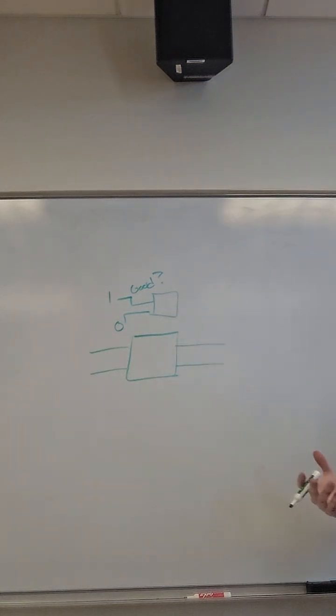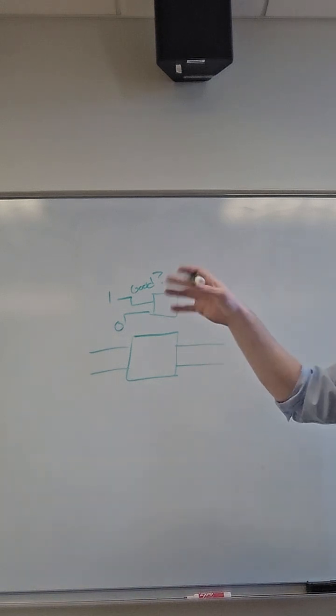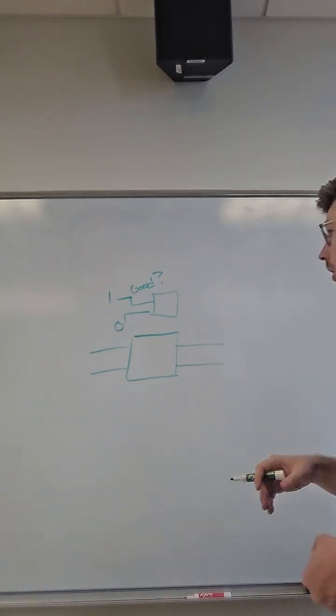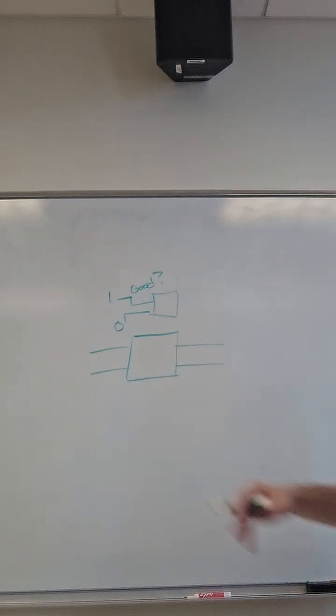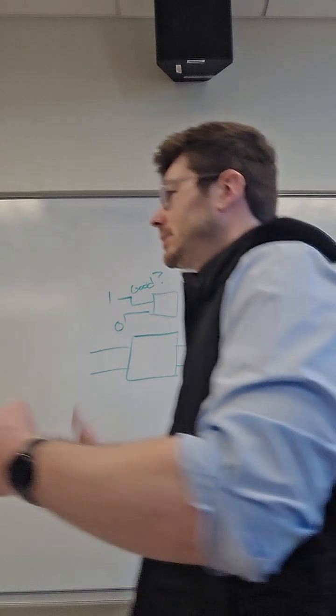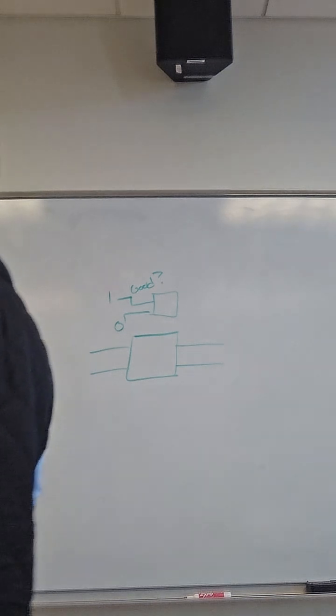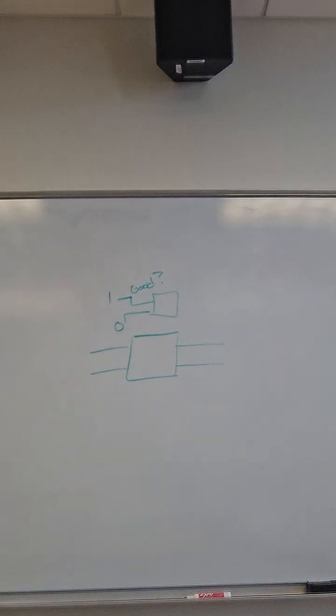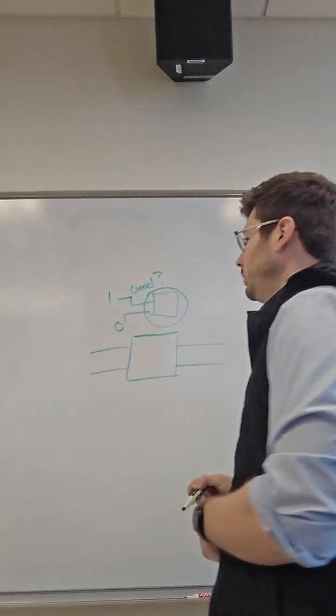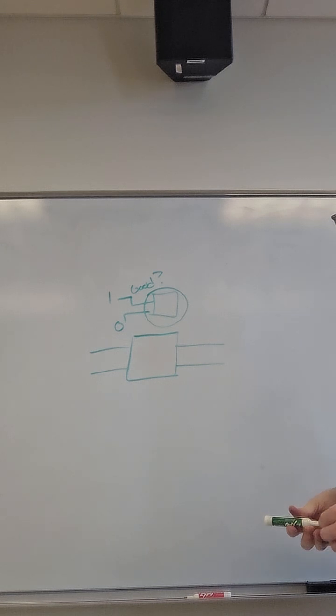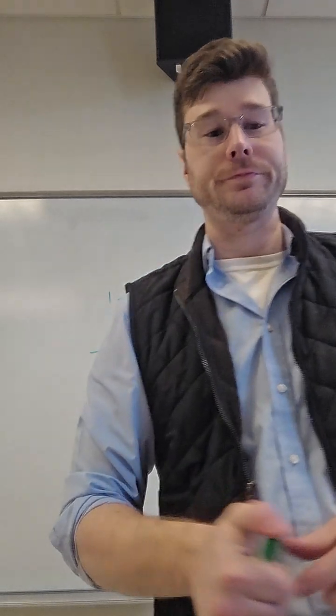There's a computer, right? A high-powered computer that's running this AI model, whatever. But all it's doing at the end of the day is toggling a line high or low, and then our PLC will react to that, right? Do we need to kick a product off the line? Do we need to sound an alert? Do we need to change something about that process, like make heaters more hot or whatever? Okay, that AI and computer vision would be a step in that process along the line, a black box that would be a potential input for our PLC. Okay, so that's something that could happen too.